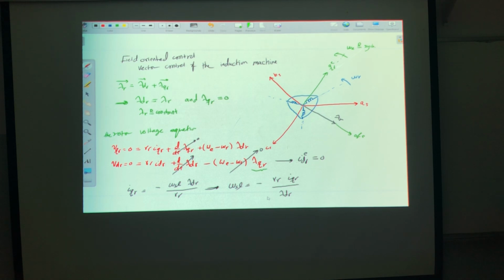In general, I cannot measure the rotor quantity. Can I measure the IQR? If I need to measure IQR, I need to measure IAR, IBR, ICR, and do the transformation, correct? And in general, I can't measure it. Someone will say, wait, you know that in the end of the day, they will have certain values. It's shorted, man. Simply, I need the actual value. So now let's see. I need to represent IQR in terms of the stator value.